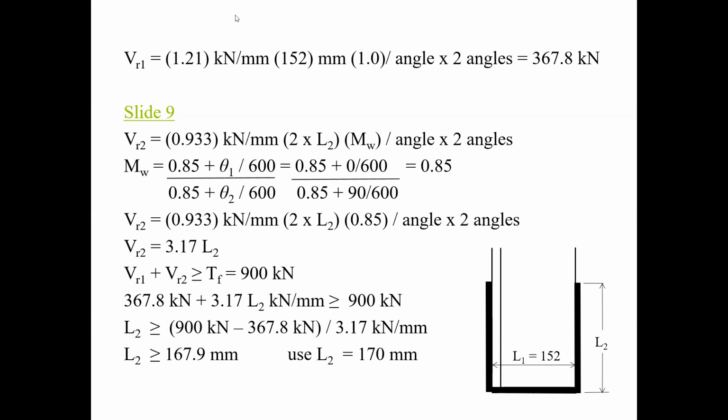And like I said, guys, even if I would end up with 160.3, go to 170. Don't round it down, round it up. Because when you go to your gusset plate, it's going to help minimize the thickness of your gusset plate and so on. So always round up to a multiple of 10. And therefore I will use here 170 millimeters. And all 4 segments are going to have 170 millimeters. So don't be cheap. Put more rather than less, because more resistance is always good in case you get an overload or a freak occurrence, there's a better chance it's going to survive that occurrence.